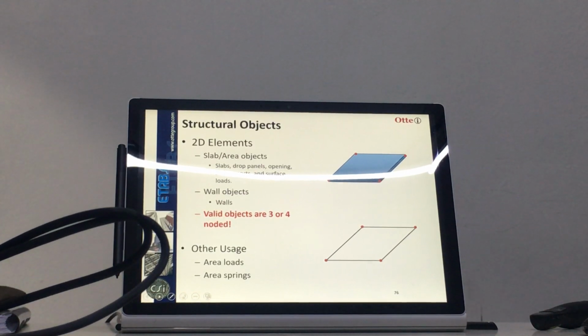Very, very simple. In the concept, in the Q4 element, this is one element, 4-sided. Need not be rectangular, as long as it's 4-sided, yeah? In the right proportion. Numerically, in finite element concept, this point, this point, this point, this point, this 4 point is called the Gauss point. Gauss point is theoretically where the result is exact, is correct. Other than that, you have no results. So now, if you use a triangle element, CST, 3-noded, right? Only have one Gauss point in the center. That's why it's called constant strain triangle.